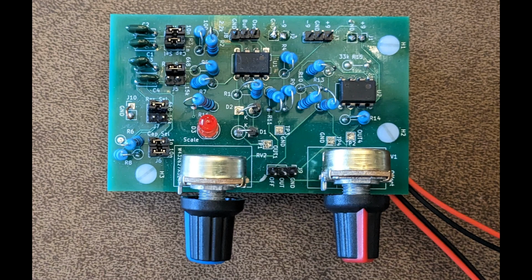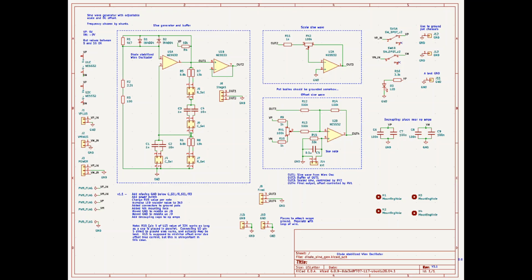To generate the signals, in addition to the M2K's signal generator, we'll use this analog Wien bridge oscillator. It's set to produce about a 2 kilohertz sine wave, and the potentiometer on the left can control its amplitude, which will be set to produce a sine wave of approximately 50 millivolts peak to peak. Here's the schematic for the Wien bridge oscillator. I wouldn't copy this. There are a few things that I'd change about it, but it's what's being used.